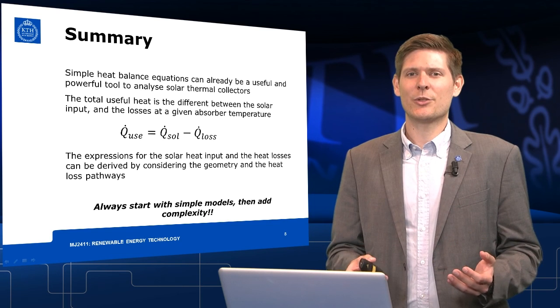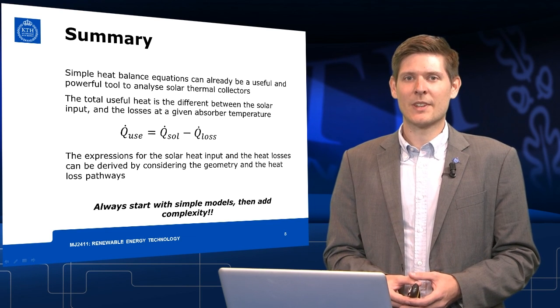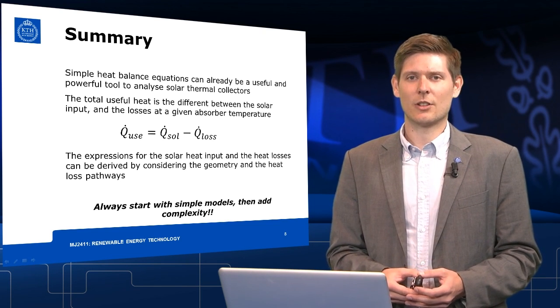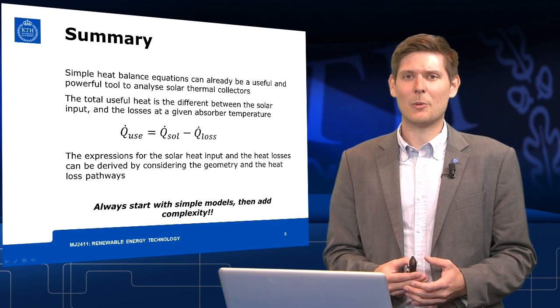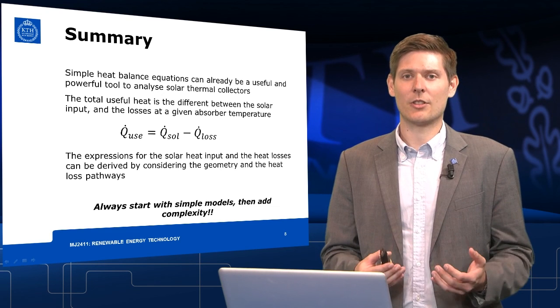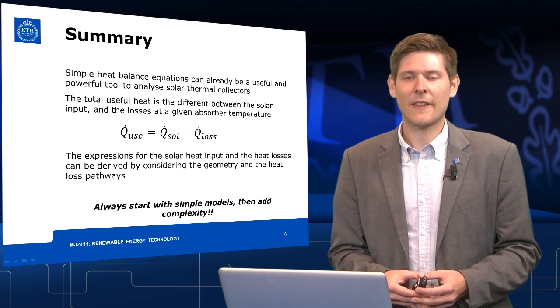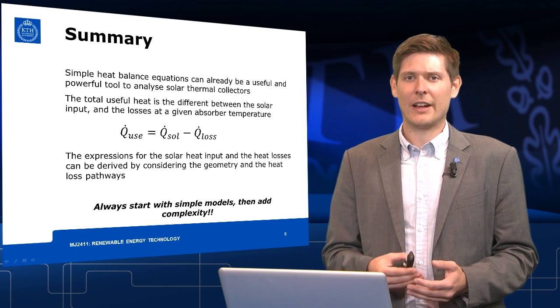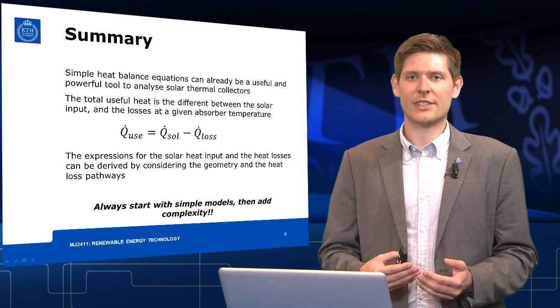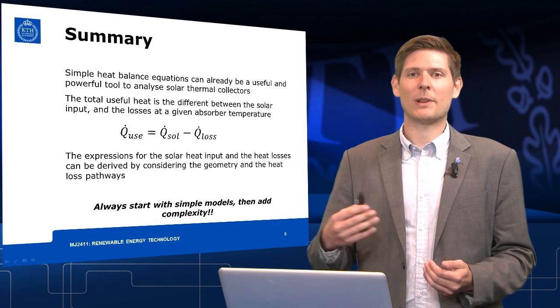What I want to stress very much is that in order to calculate a solar collector, you need to be aware where to draw your boundaries, where you're going to have your control volumes, and you always want to start with a very simple system, and once you have established a very simple system, you're going to add complexity.